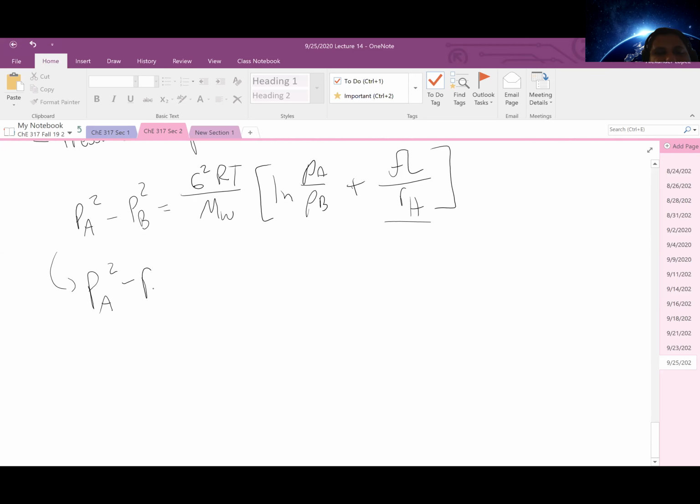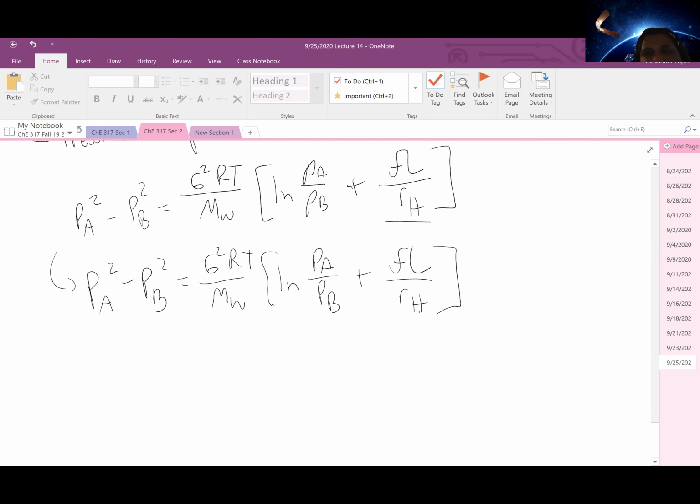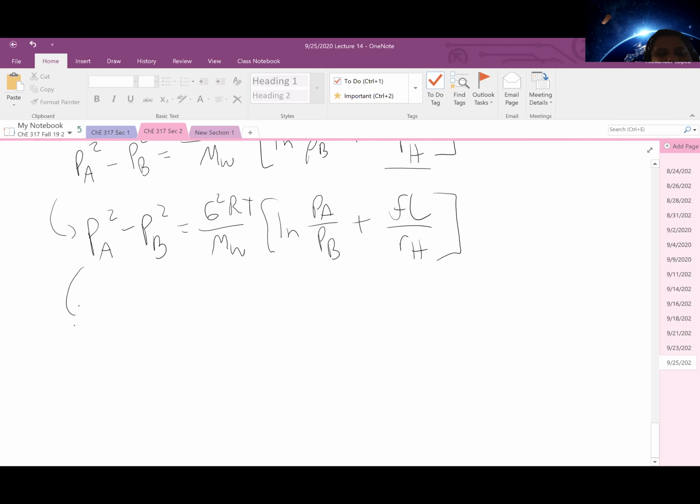One of the more helpful ones for your homework particularly is, in lieu of a ratio of densities, you can simply look at the ratio of pressures. By assuming an ideal gas, the ratio of densities and pressures will be the same. Another form that can be used is this one shown here, which eliminates the squares by instead looking at an average pressure.